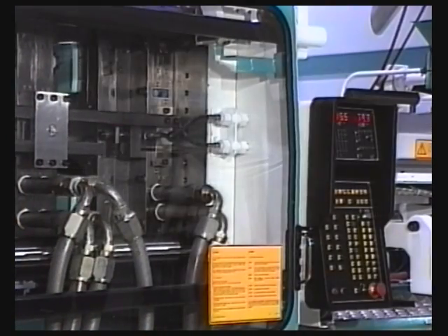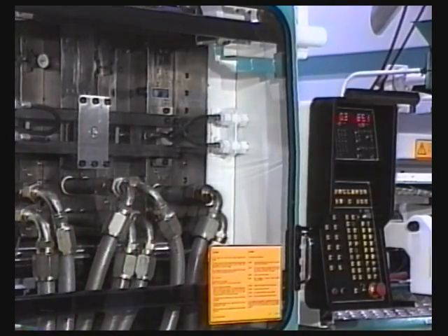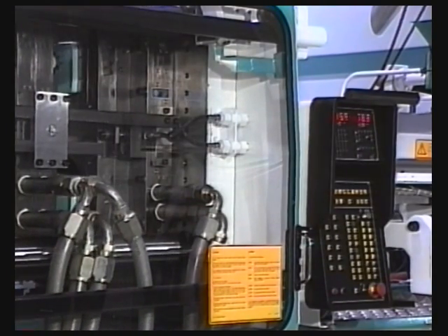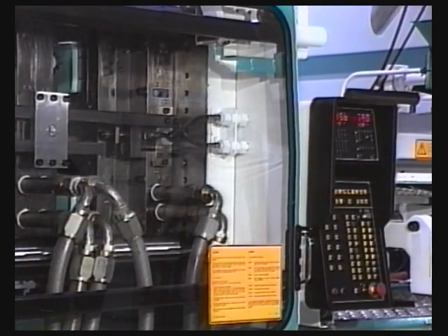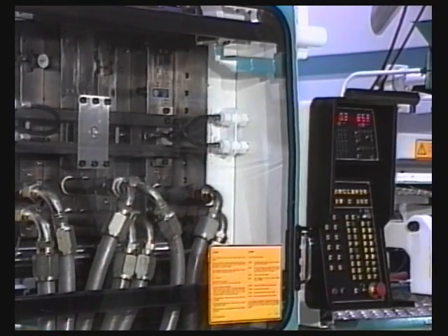It is important to realize that whenever the barrel temperatures, screw speed, or mold temperature is adjusted, the effect may not be seen for 30 to 45 minutes. On the other hand, results of changes to pressure, speed, or position can be seen almost immediately.